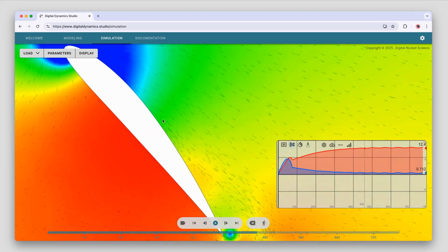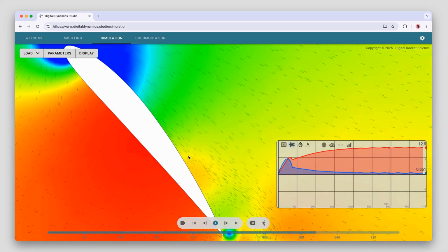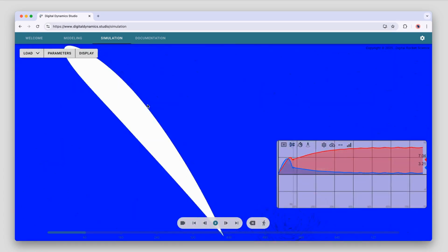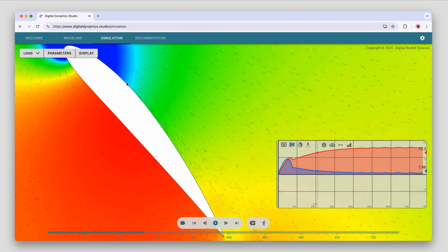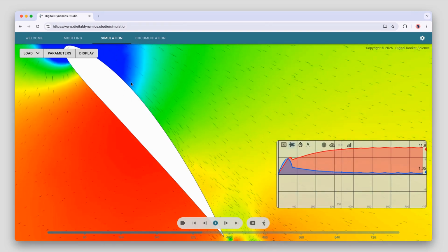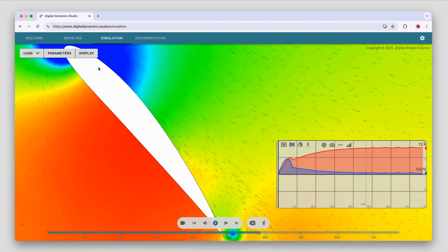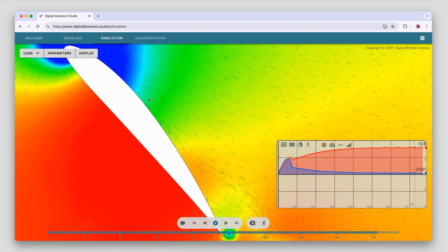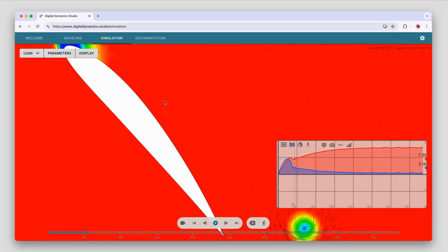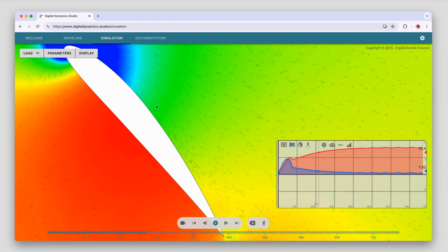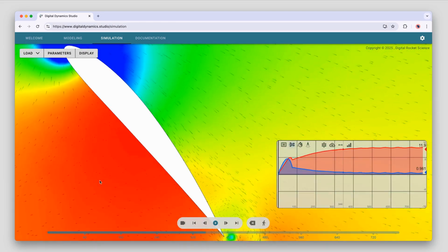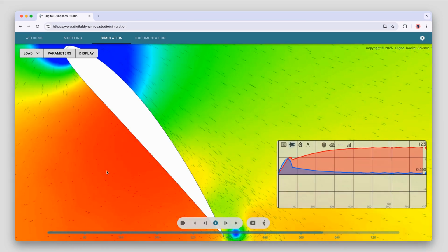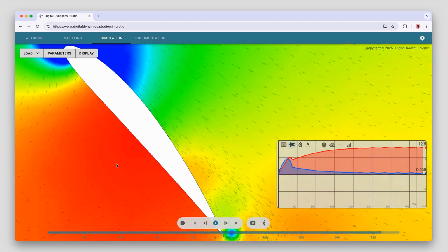The fact that it is so attached to the flow, at least to this point here, is because the slip boundary condition is not a physical boundary condition. There would be a boundary layer in reality, and that boundary layer will cause the air to separate from the airfoil and stall much earlier than this case of 50 degrees, probably around 20 degrees, 25 degrees. So this linear relationship between lift and angle of attack really only goes up to, say, 20, 25 degrees, depending upon the airfoil type.